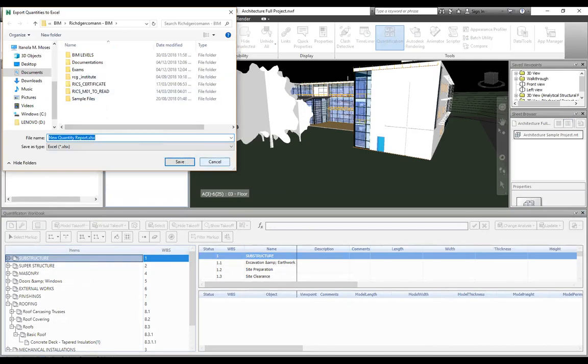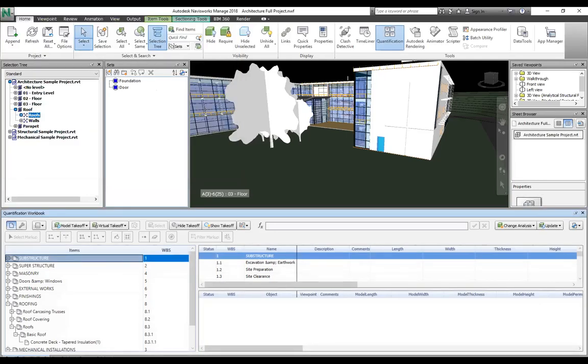So all of these quantities might not be very interesting until we begin to add cost to it. 5D, which is the fifth dimension of BIM, deals majorly with cost and not quantity. And that is why it is required that when we begin to also add the timeline too, if we have our cost, we can attach the cost information there, so that when that schedule is being done, the cost information is also showing.